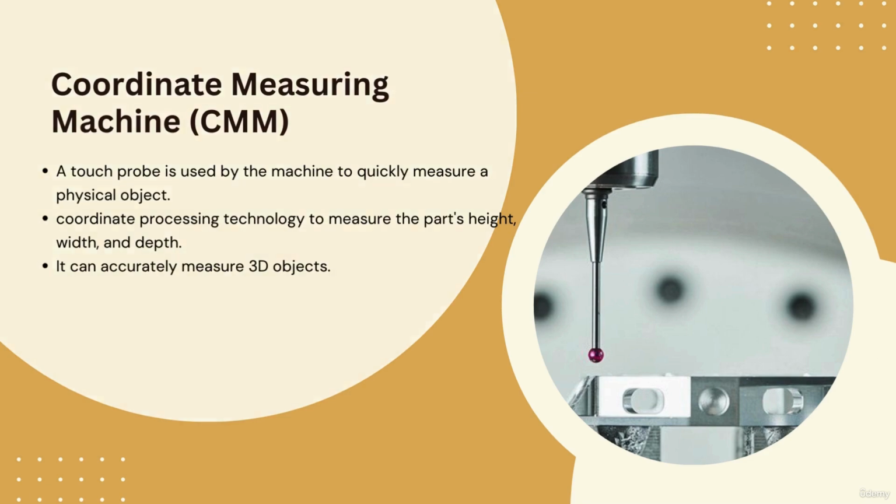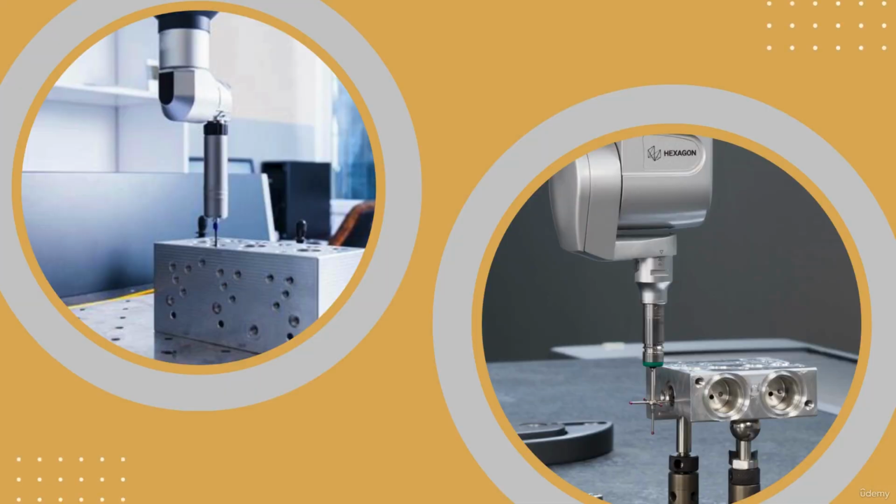Look at it. Just place the components at the particular locations, holding them on either a surface plate or some kind of flat face in the machine itself. Once the part is placed, it can be measured by touching the probe at each location, random locations, and every individual corner. Once it is measured, it calculates an arithmetic mean, then finds the exact value to know the difference of this tolerance zone. Okay, these are the machines.